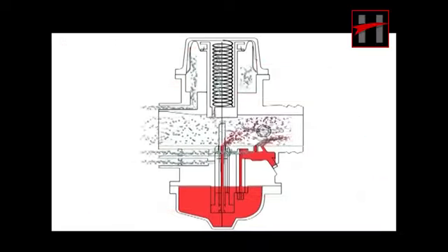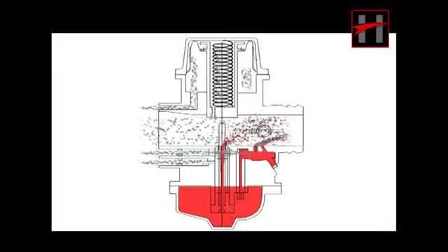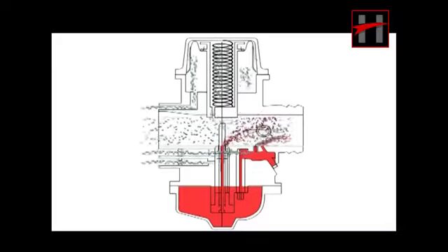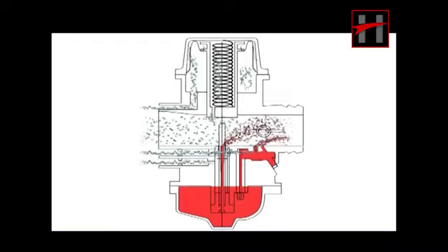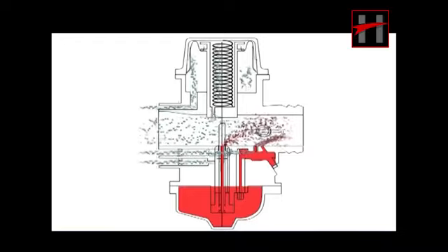At full opening of the butterfly slide, the piston valve is lifted fully along with the jet needle, and fuel is supplied mainly through the main jet.